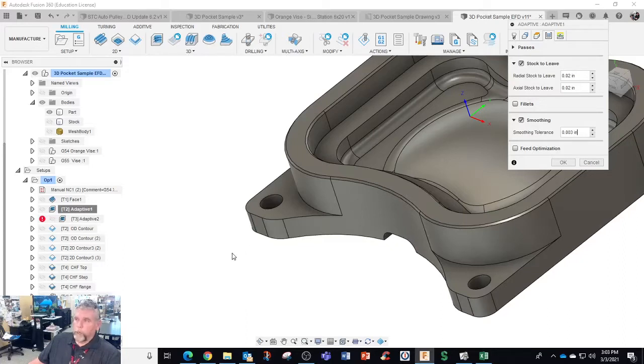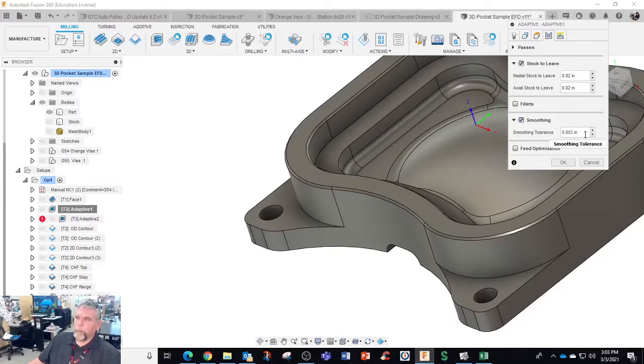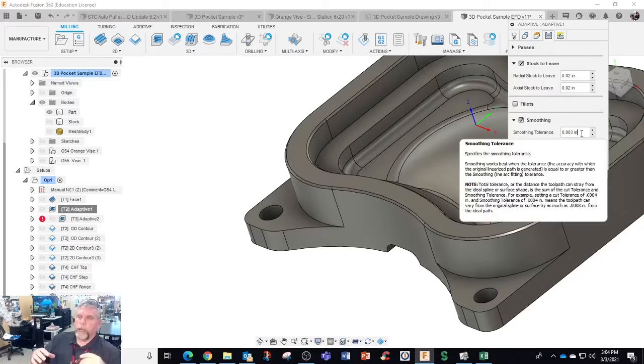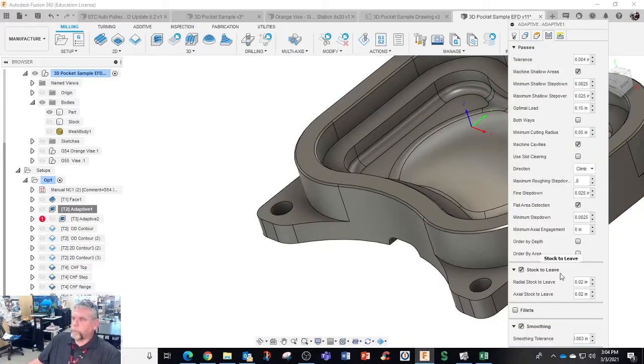it's going to create a lot of code, and it's going to try to do all G1 moves, even in curves. Most machines can do arc commands. Like to do this arc can be done in one command, versus little tiny lines. So by turning on smoothing, and I put a rough tolerance on there, better than what the part should be, then I can start to turn any potential lines into arcs, so it kind of shrinks the code up. It also helps processing time. So there's a lot of settings in here, but they're kind of dynamic on each other.